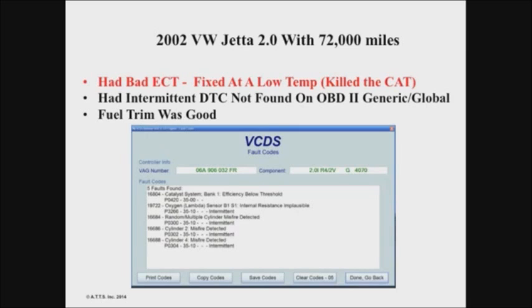Also, since I'm on Volkswagen Audi, these have a lot of problems with the air injection systems, don't they? The little rubber hose, the vacuum hose, breaks, and rather than letting the air shoot out to the atmosphere, or under the hood I should say, what's it doing? It's blowing upstream all the time. Lean condition, rich command, you pull that dipstick out, man, you got gas in that oil big time. A lot of the fix is fix the hose first. If you get the cat in time, drain the oil and filter, and drive this thing, and you'll notice your code will go away. Sometimes if it's too far gone, not only do you need the sensor, you're going to need the cat. In this case, it's a little different.